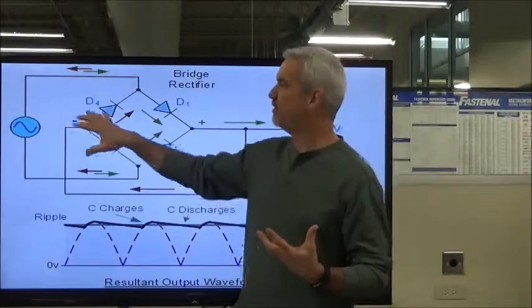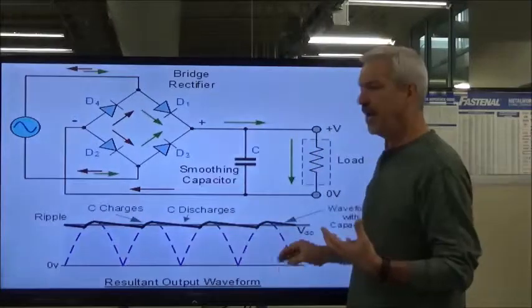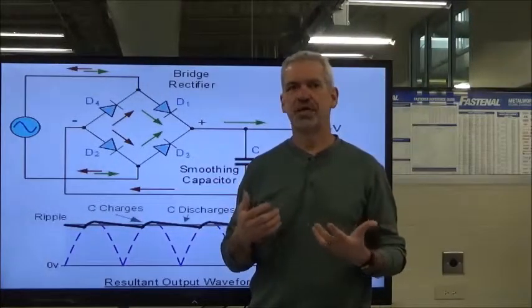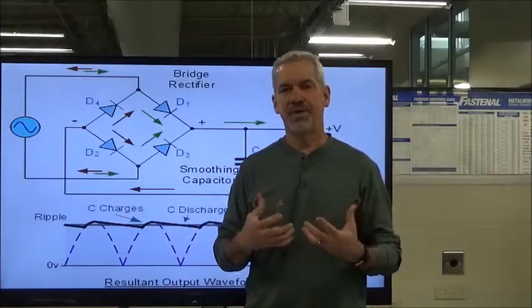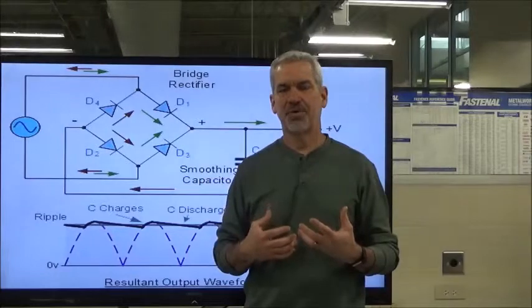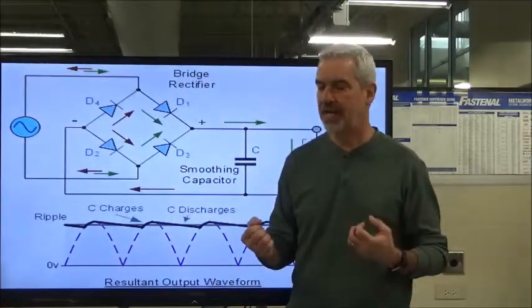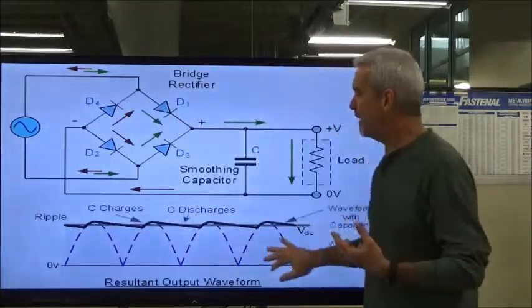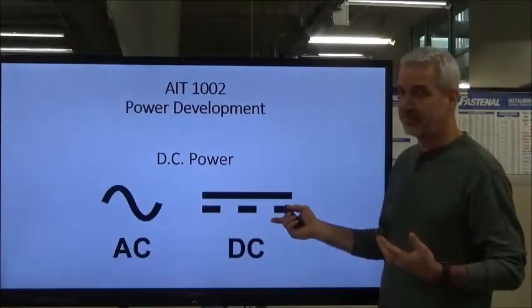You step that voltage down, you rectify it, and get a nice smooth ripple, and you rectify it to DC. Some phones are like 9 volts, sometimes they're like 5, 7 volts, something like that. But anyway, that power supply gives the correct voltage going into whatever device it is that you're using or trying to charge. But anyway, that is the bridge rectifier and how we convert AC to DC. That's how it's done, okay?